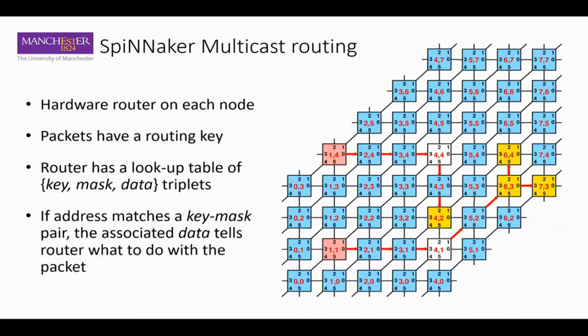And because each chip is connected with 6 of its neighbors, we can send packets along through routers on each of the chips in hops. And we pride ourselves in having a multicast router technology, so a spike can be replicated on all of the 6 links, plus into the chip, at once if needed.